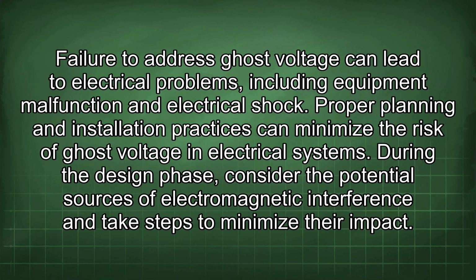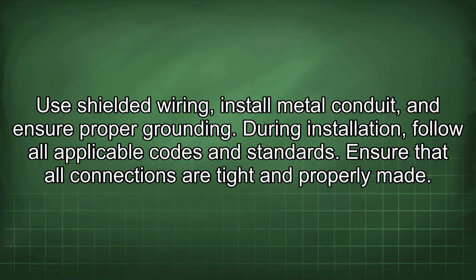Proper planning and installation practices can minimize the risk of ghost voltage in electrical systems. During the design phase, consider the potential sources of electromagnetic interference and take steps to minimize their impact. Use shielded wiring, install metal conduit, and ensure proper grounding.